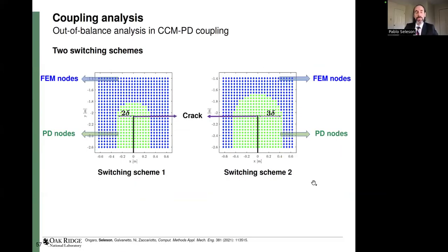And because of that, we are going to apply a decomposition of the domain so that we have peridynamic nodes surrounding the crack, in particular the crack tip, and outside there is a transition to the finite element nodes. Now, because we know that errors depend on these high order derivatives, we would like to explore how far one could have the interface from the crack. So we hypothesize that if our interface is farther from the crack, then we are going to have the errors more under control.